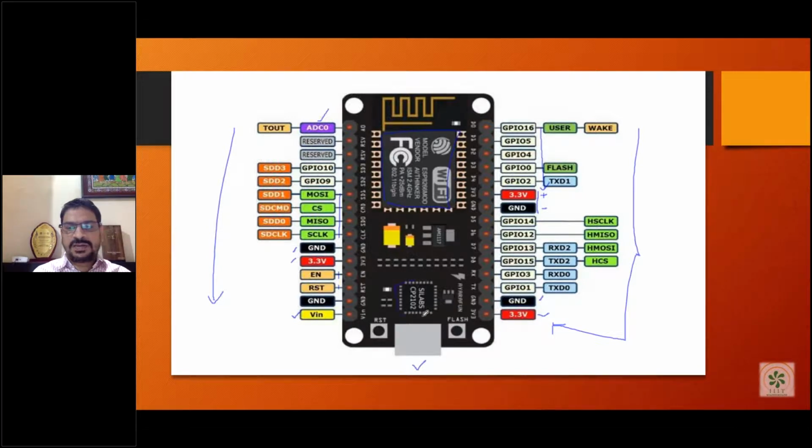Here we have the microchip, which is also for programming. We have a reset button here and a flash button here. If we have a program which we have put into the hardware and we want to reset it, we can do that, or if we want to flash it, we can do that. So this is a brief introduction to the chip called NodeMCU. The microcontroller inside is the ESP8266, and it is Wi-Fi enabled, meaning we can connect this device to Wi-Fi.